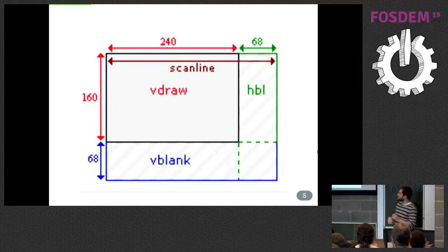So you have to synchronize your code with the hardware to only write to the video memory in the vertical or horizontal blank. This is quite tricky to get right. And what we thought is, if we start writing the compiler, it's going to be really difficult to get any feedback. You have to get pretty far just to get something on the screen.